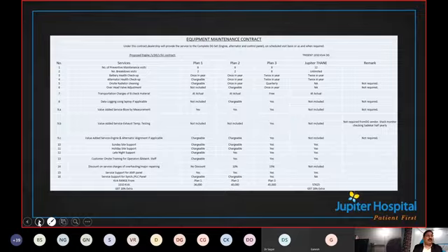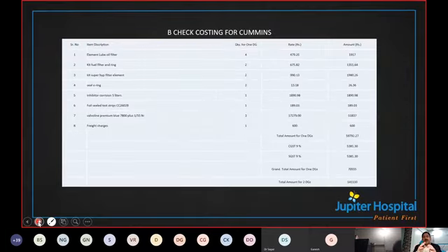So moving ahead, as I told you, in DG also, we cannot say that we are not doing it. Maybe the B check is after 500 hours or maybe 6 months. Then the C check is maybe after 15,000 hours, or maybe after 2 years, or one and a half years. All these things, B check, C check, you need to do regularly. This is what the costing is. The costing is not much, like for a 1000 kVA it's like 60,000. But we cannot ignore that, because these are services and we cannot ignore them. So please do not do that. These are the things which are important. Please close the deal prior to closing the entire equipment deal, on what it will cost for A, B, C, D checks, and you will get a good deal at the time of procurement.